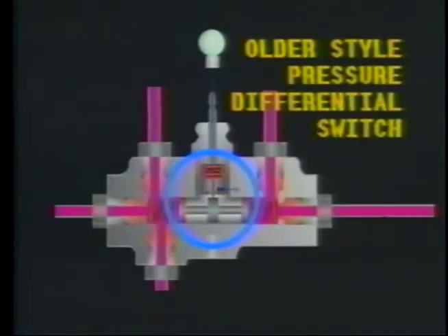On most models, this piston is spring balanced, so the piston recenters as the brake pedal is released. This, in turn, turns off the warning light. On some older models, if a failure occurs, the piston will remain off-center, and the light will remain on even when the pedal is released. After repairs are made, the valve has to be reset by manually removing the switch assembly to allow the spring-balanced piston to recenter. So you can see that Technician B's statement is also true.